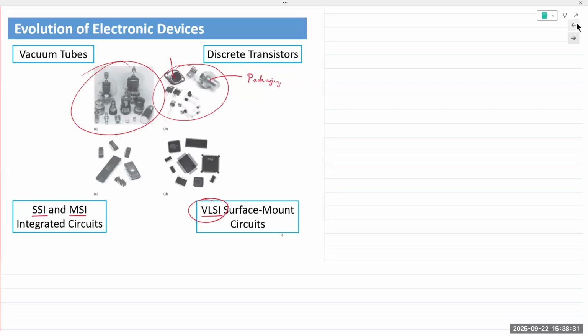Inside a clean room, it is less than 1,000 in academic clean rooms. When I went to grad school, I worked in a clean room that had 2 bays which were class 100, meaning less than 100 particles, compared to a couple of million outside. Industrial clean rooms, it's less than like 1. It's that clean, and that's why it's known as a clean room. If you ever see a medical show, sometimes patients are inside behind filtered lines, and they say that's a clean room. Everybody's gowned up to prevent contamination from germs and bacteria.